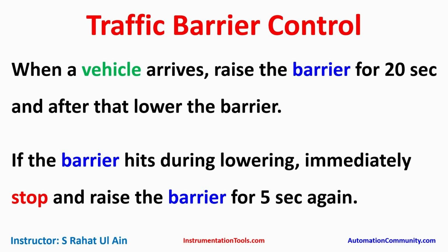So for this example, we will use normally open contacts. We will also be using memory bits. With that, we will be using some timers like TP and TON. So let's move to TIA Portal where we will draw a ladder diagram for this traffic barrier control example.